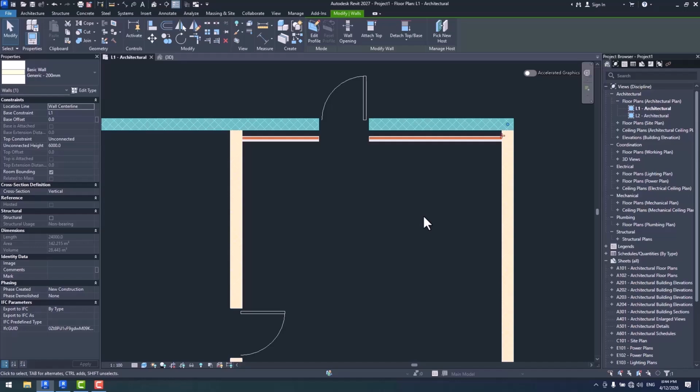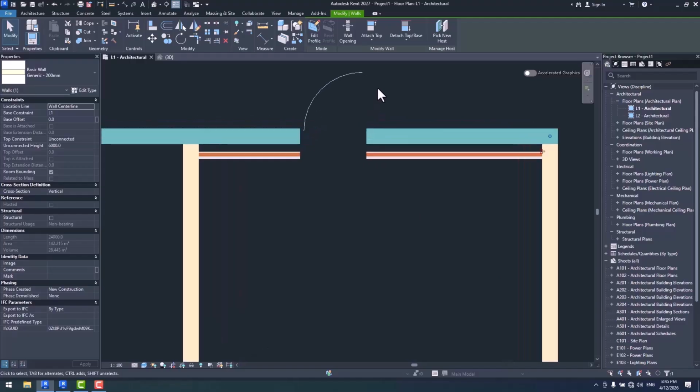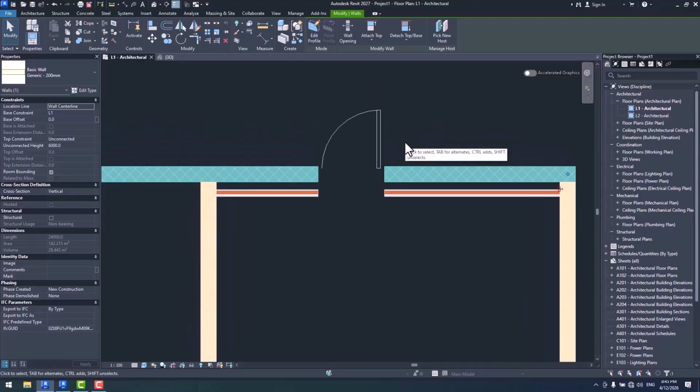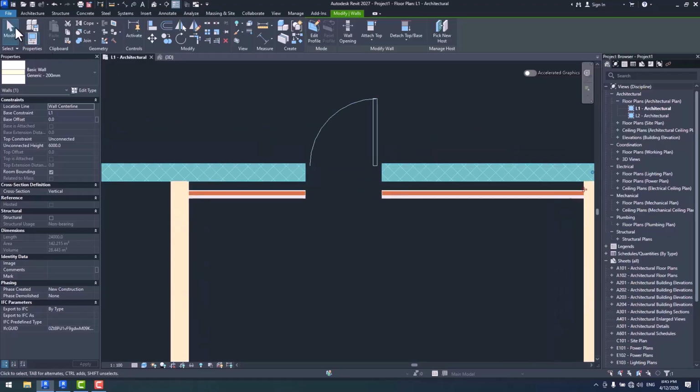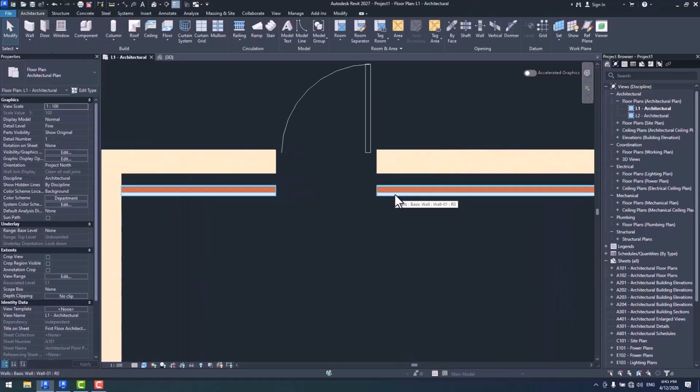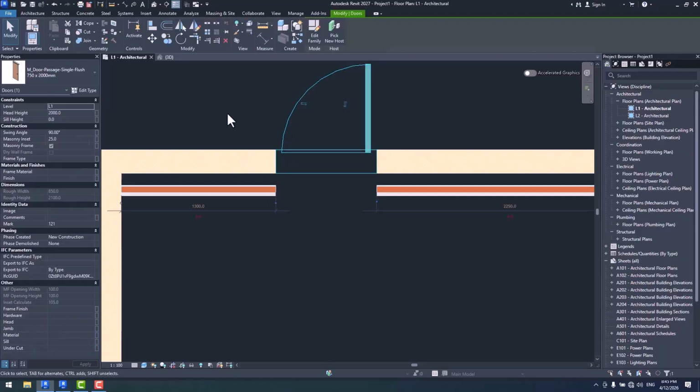I mean, as you can see, version by version, it adds or provides us with more and more options and items regarding the matter. However, guys, there's actually a downside to this. When setting the layers separately, it doesn't really matter which technique we're using, like hosted walls, auto join, or any other thing. The downside is that when placing the doors, guys, the door frame won't be extended according to what we have in the layers.